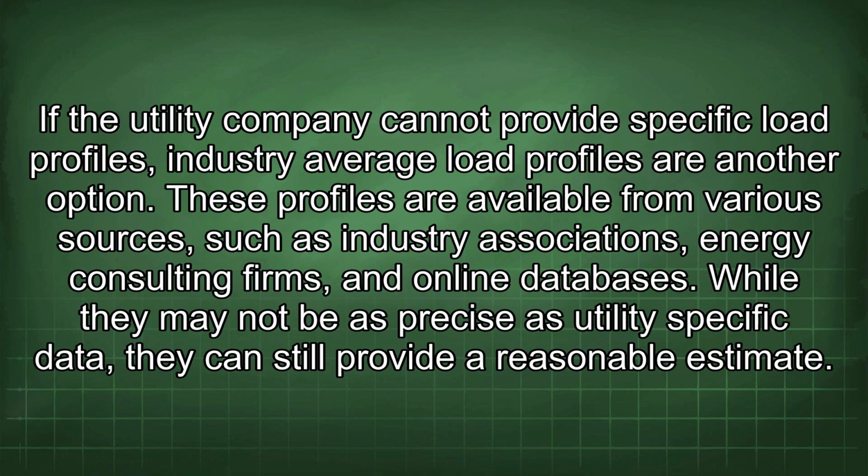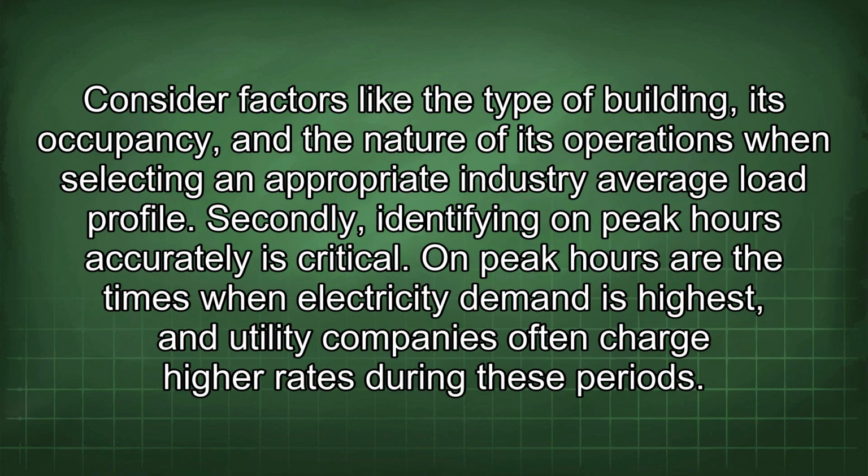If the utility company cannot provide specific load profiles, industry average load profiles are another option. These profiles are available from various sources, such as industry associations, energy consulting firms, and online databases. While they may not be as precise as utility-specific data, they can still provide a reasonable estimate. Consider factors like the type of building, its occupancy, and the nature of its operations when selecting an appropriate industry